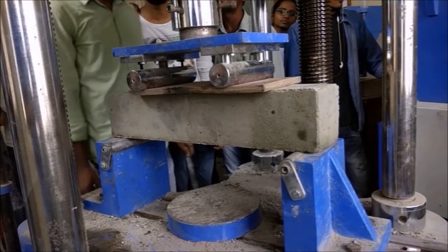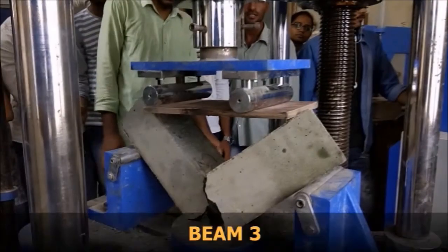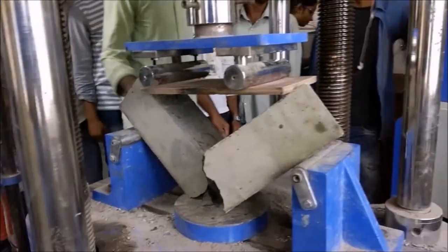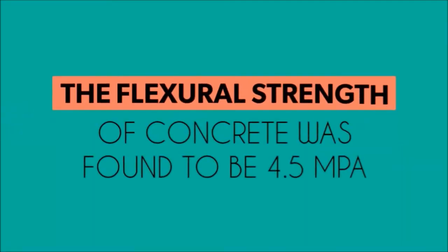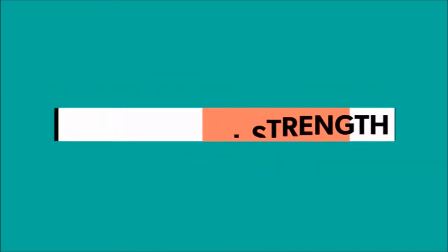This is the third beam. We have casted 3 beams and 2 have failed, and this is the third beam. So the results we know, or to be more precise, the flexural strength of the beam is 4.5 MPa.